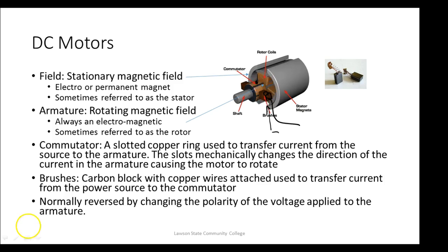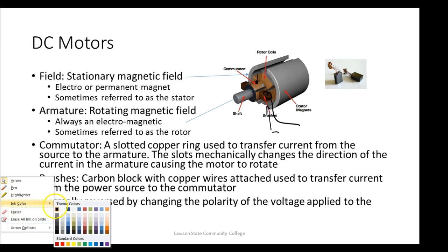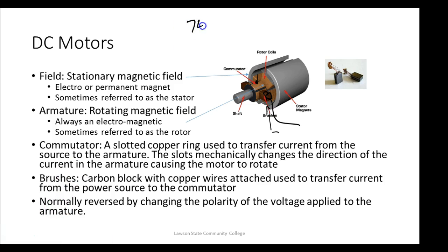So we came up with a relationship between horsepower and electrical motors. A rule of thumb, guys, and it's not 100% efficient but works out good enough for calculations, is 746 watts of power per horsepower. So if I wanted to figure out how much current a motor would draw, I would take the size of the motor in horsepower, multiply it by 746, and then divide that by something.